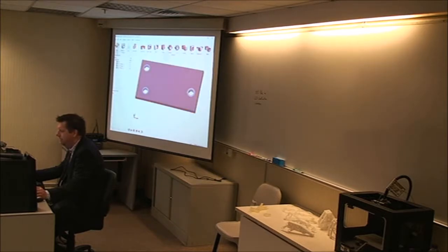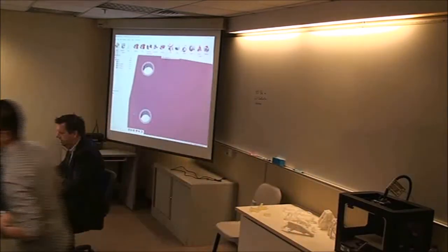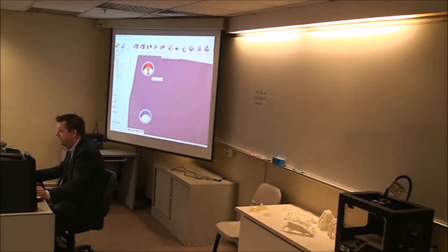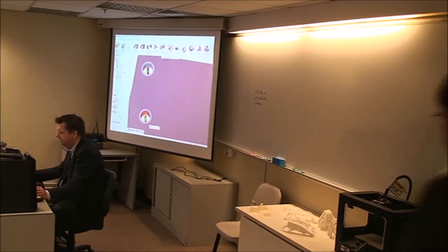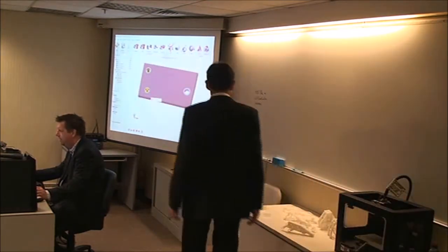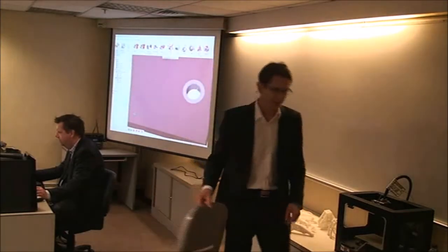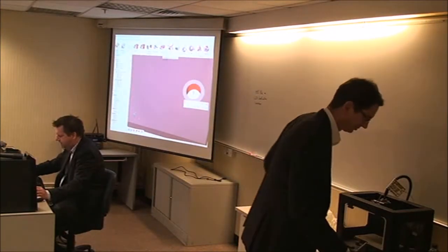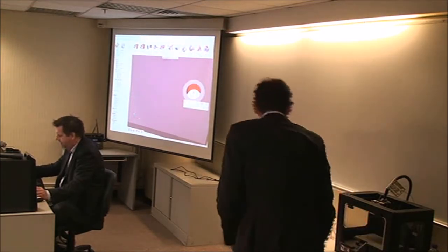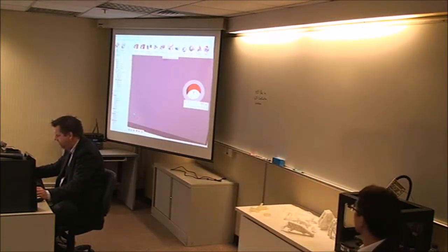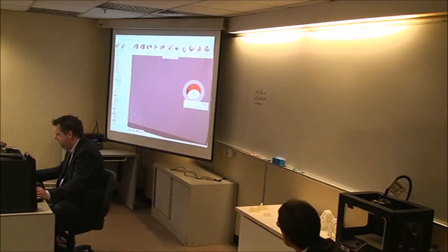I want to put loads on this model, so I go to structures. I can put supports on the holes. Again, it's all very graphic. I can double click that. That means it pivots about that point. I can put a force into this hole and say how big it is, maybe 2,222 newtons, in which direction, Y direction.